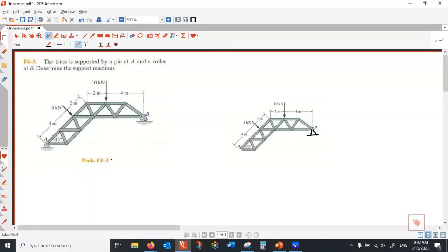This is called contact. Contact is whether you have a roller against the surface, or you have cylindrical faces pushing against each other. This is called contact. Whenever there is a contact, how do you find the direction of reaction? First, you have to visualize if that was going to move. What was the path of movement? Here, if that was going to happen, the path of movement was like that, right? I call this a sliding direction. So normal to that sliding direction, that's the reaction force.